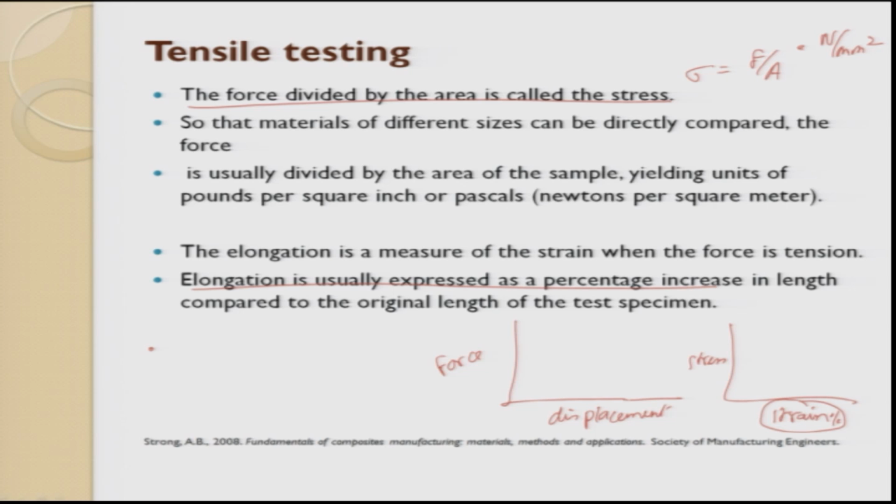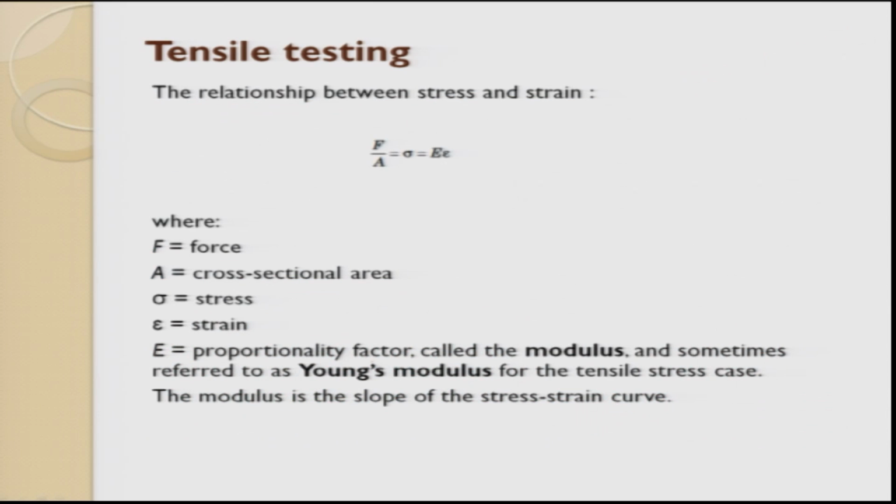Till now we have been happily using only uniaxial tensile testing. That means a sample is tested in one direction. Today there is a concept called biaxial testing. Biaxial testing is a new phenomenon wherein the loads are applied in one direction as well as at 90 degrees in the other direction. New machines are getting developed. People are talking about this concept because they realize that biaxial testing results are more reliable than tensile testing.